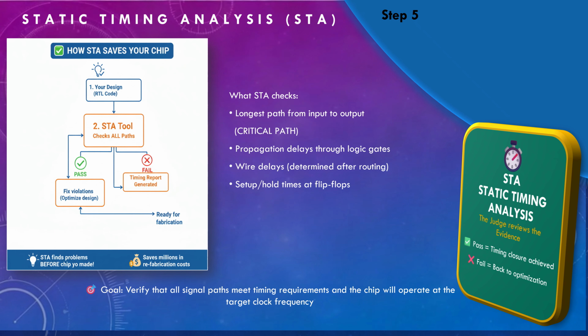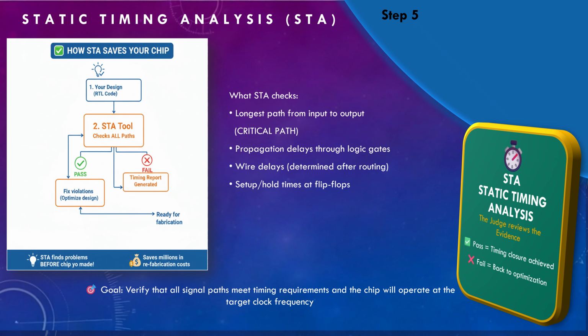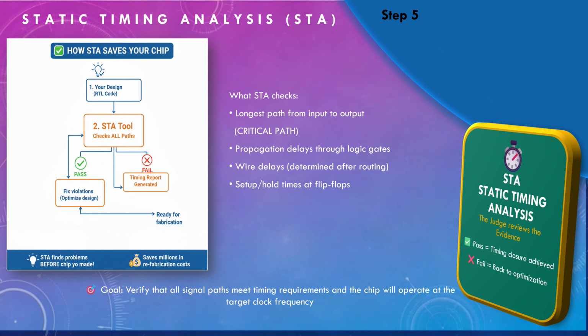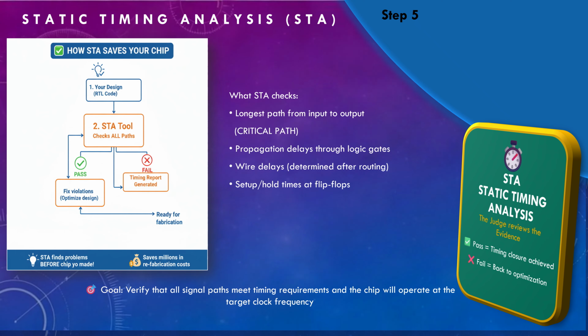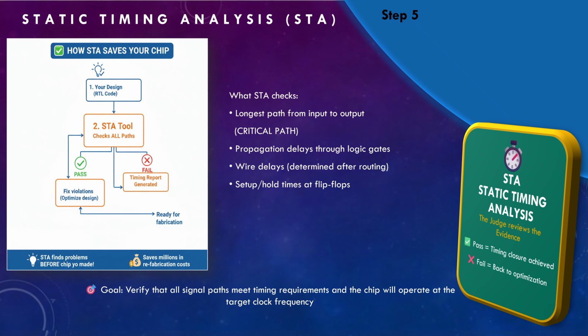Adjust placement, add buffers. The truth is timing closure is iterative. You rarely get it right the first time. If timing has ever ruined your day, welcome to the club. Goal is to verify all paths meet timing, chip operates at target frequency.